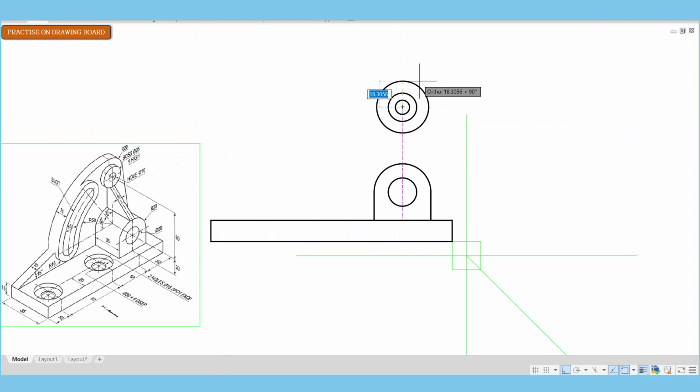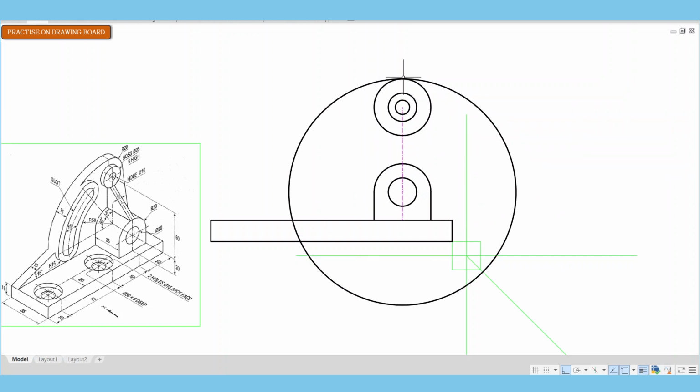And then from that same center, I would draw the tangential arc with radius of 20. And then I go back and I draw the interior tangency circle, radius of 80. And then I'll draw the slant line from that edge. And what I need is for that slant line to have an angle of 15 degrees.